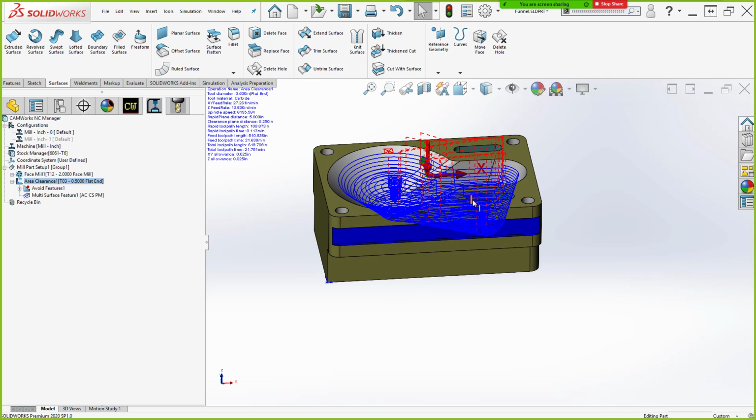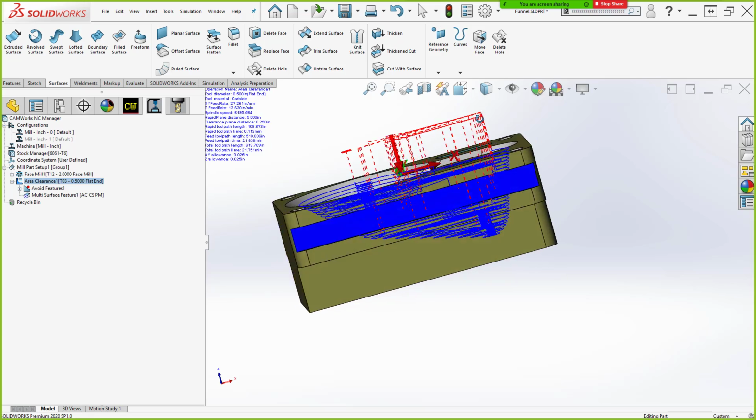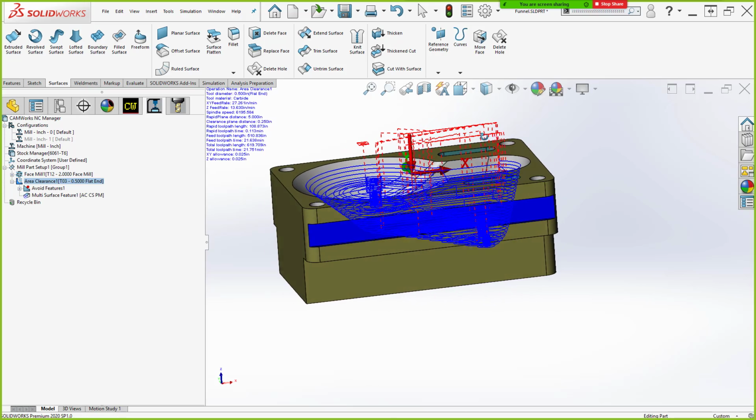So using all displayed, filling in some surfaces where there's holes and inconsistencies or non-continuity on some of your multi-surface features, filled surface can come in, you use all displayed, use a couple of contain and avoid areas. It's one of the quickest, most effective ways to program.